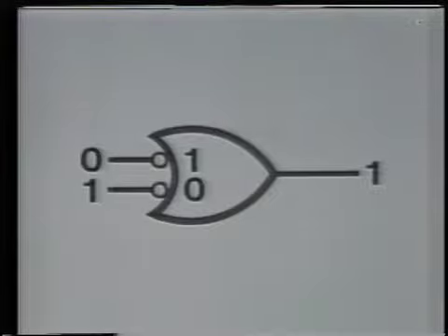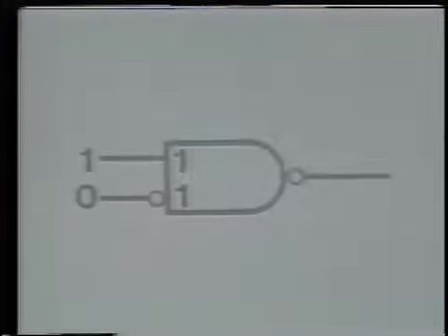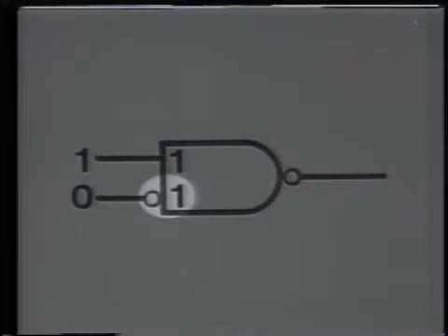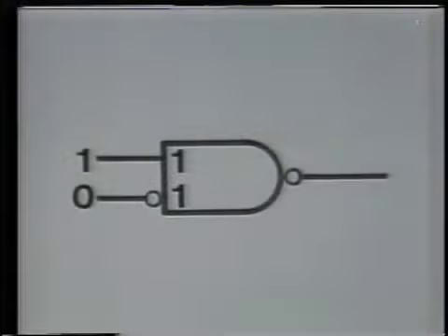in separate steps. If you have an inversion, determine what the effects of that are going to be. If it's followed by a logic gate, such as an AND gate or an OR gate, determine what effect that gate will have on the signal. If there is an inverter on the output of that device, determine what effect the inverter will have on the signal. In other words, break the circuit down and take the analysis one step at a time.